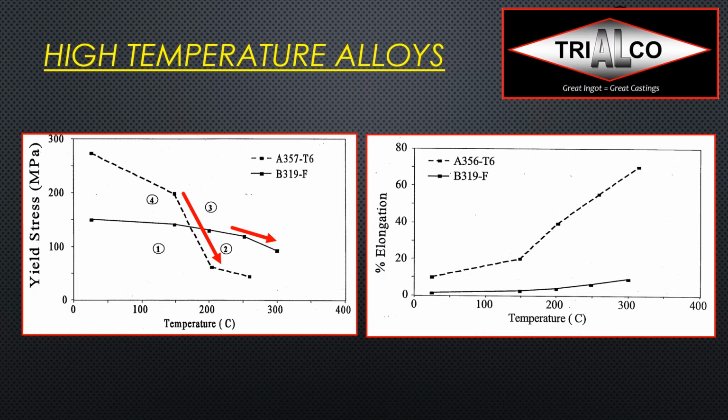That is a lot better when I add copper. First of all, it is pretty stable now until about 250 degrees Celsius. And even after that, the drop within 50 degrees is not 75%. It's really just a slight drop. So that's very important. This is why we are adding copper.